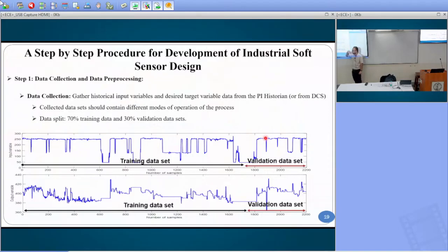I can't simply judge whether this point is a good point or a bad point. What I can judge is that there are multiple changes happening like this. It's not an outlier, it's not occurring at one instant. It is occurring at multiple instants at frequent intervals. So there is a process change.